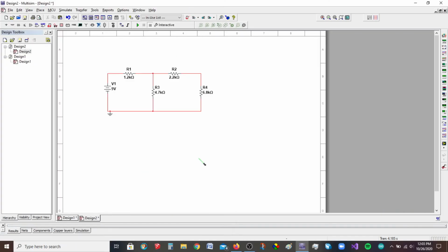Okay, and so now I'm just going to put an ammeter in here because this is our original circuit, and we should be expecting, what did we say, 719 microamps. So let's see what happens. There's 720. I'm happy with that. And we also had a voltage drop across the load of 4.89 volts. So let's try that out.